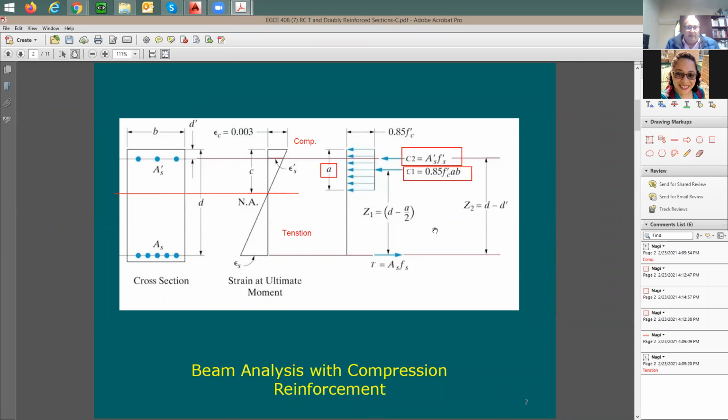The problem in here is that you don't have this Fs. You don't have it yet. But usually we assume it's going to be equal to Fy. And then we confirm that the steel is really yielding when you check the strain in the steel, and then you say it's going to be more than 0.002, 1 for grade 60. So I'm going to have here one issue. This is going to be the second, and this epsilon or Fs prime is going to be the third one.